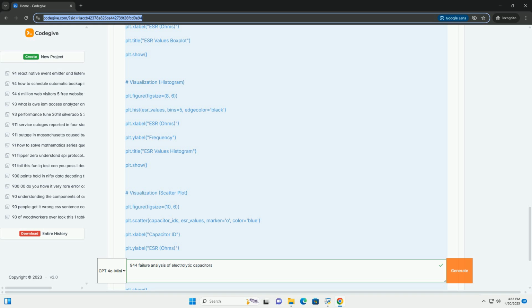Diode test, in circuit, very carefully: some multimeters have a diode test function. You can use this to check for a shorted capacitor in circuit, but you must be extremely careful to avoid applying a voltage that could damage other components. If you see a diode reading, low voltage drop, across the capacitor, it's likely shorted. Always disconnect power before testing. This method is generally not recommended for in-circuit testing unless you're very experienced.